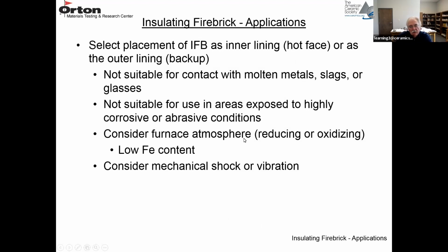And the furnace atmosphere may have an effect. If it's highly reducing, you may have to have a low FeO content because it may reduce or oxidize materials in the IFB. And you have to be aware of mechanical shock or vibration because these are relatively weak materials.